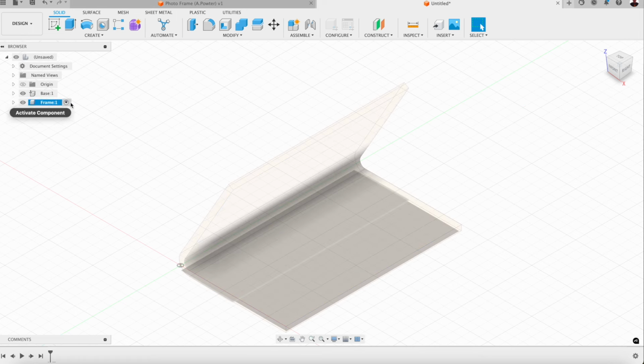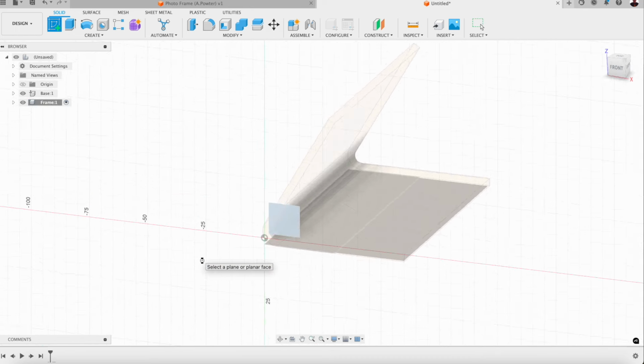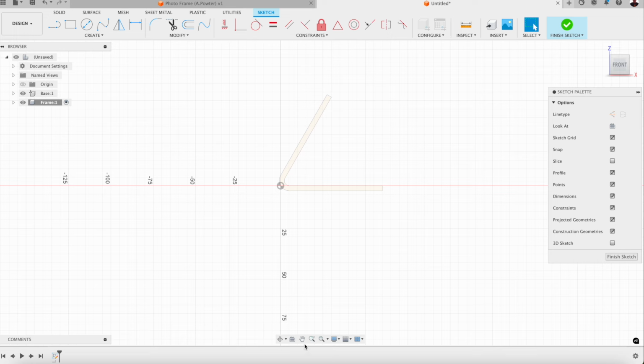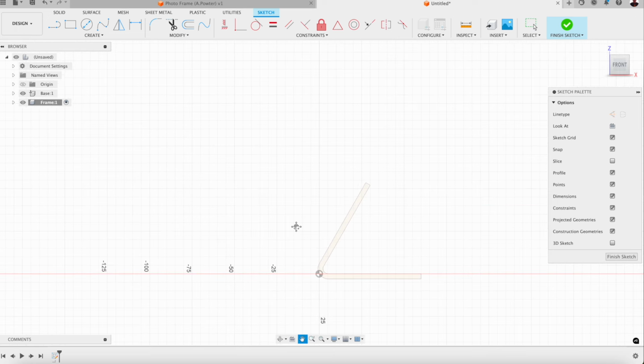Notice here that it's created and the black dot is now selected. Create a sketch. We're going to pick this front window here. And I'm going to zoom out and use my pan tool to drag that down and press escape. I need to draw 2 lines. I've got snap to grid turned on. You'll notice it's snapping. If I click on the grid, I've got it turned on. Yours may be turned off or turned on. You can toggle between if you need be, right?